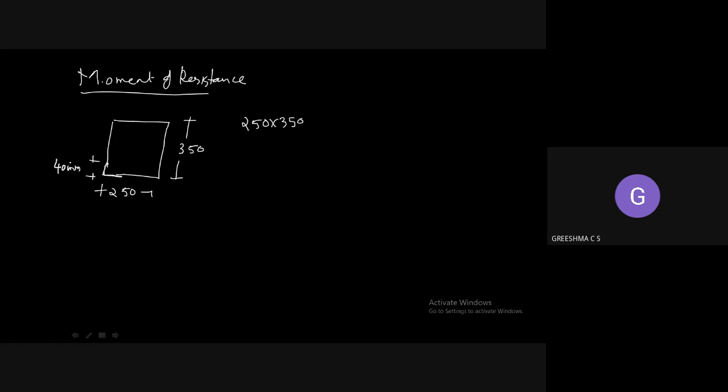At the 40 mm distance, 3 bars of 12 mm dia are placed. We have used M20 grade and Fe 415 steel.